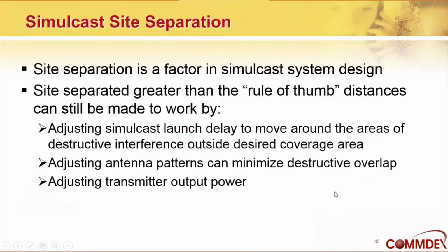So again, this course is not about designing systems, but the people who do design them have to keep all that in mind. Those are rule of thumb distances, rules of thumb. We can adjust the simulcast launch delay, adjust the antenna patterns, and adjust the transmit output power to give us the coverage we want.